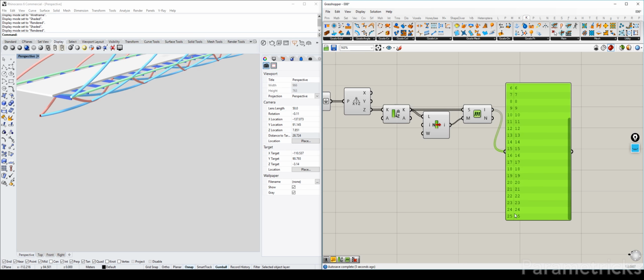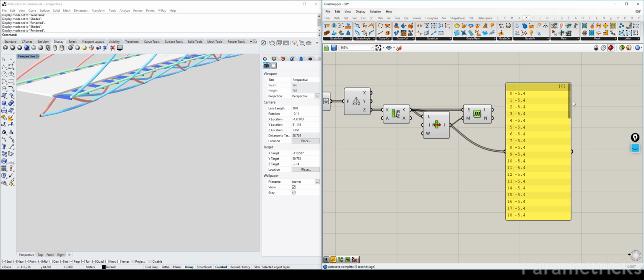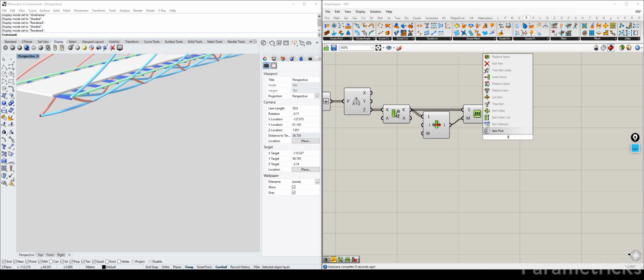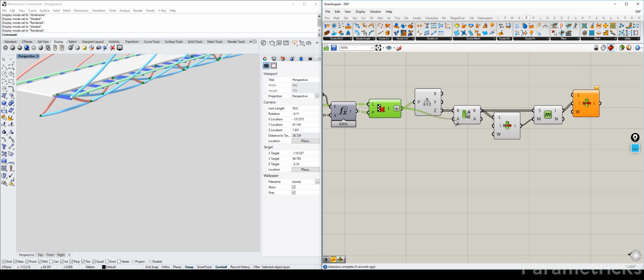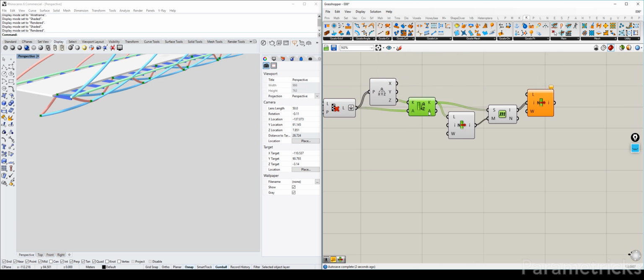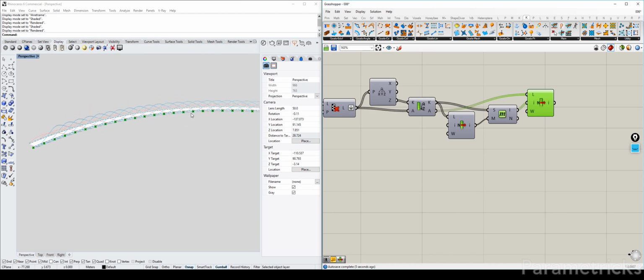And it found it within the first 26 numbers, because 0 is also counted in. And if you look at our sorting process, we do have 26 of those lower numbers. So with that, we can just do another list item using the indices that we got. And one thing to not forget is to also give that to the synchronized sort, so that it's sorted accordingly, and select that point instead. So now we have all these bottom points selected.